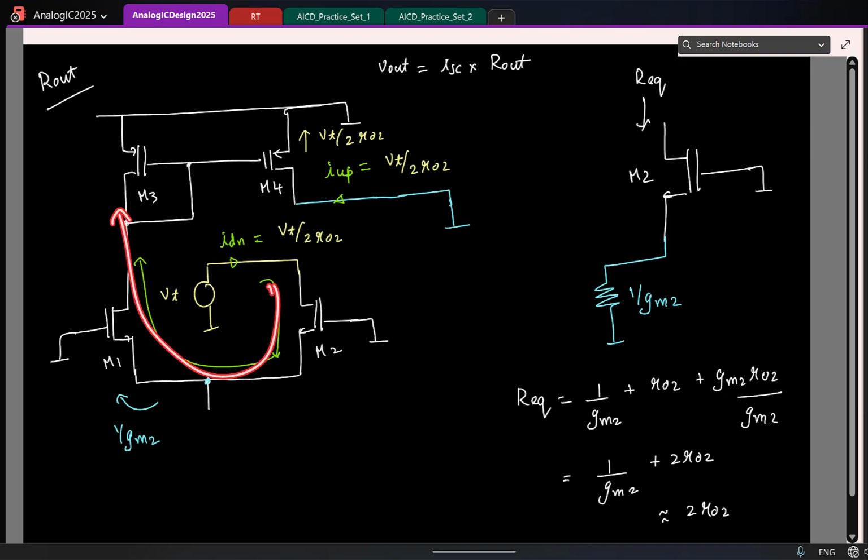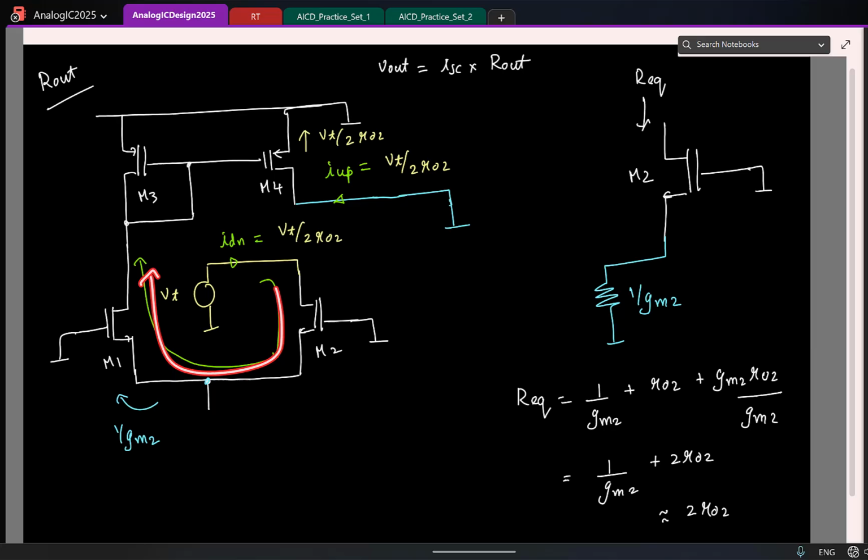Okay. So you're okay that the same current will flow through M2, right? Which means the gate voltage here will be set to a value to make sure that the current in the transistor M3 is equal to this, correct? So which means the same gate voltage is fed here. It's current mirror action, yes. Sir, but we are using the threshold of NMOS only. Threshold of NMOS, I didn't understand.